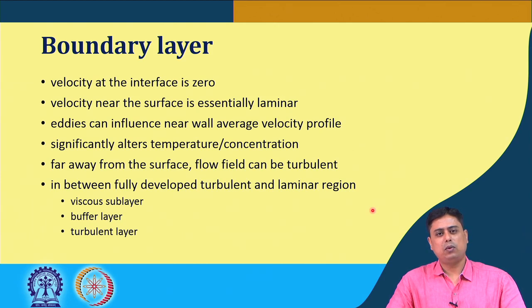But sometimes, although the fluid happens to be laminar in that layer, eddies can form, due to turbulence or some obstruction or some influence of the geometry, that creates some eddies or wake. That alters the flow profile in that layer of the laminar flow, and then it influences the near wall average velocity profile. But it hardly changes the overall profile at the bulk velocity.